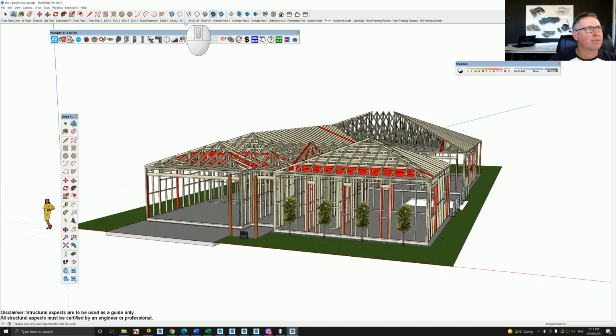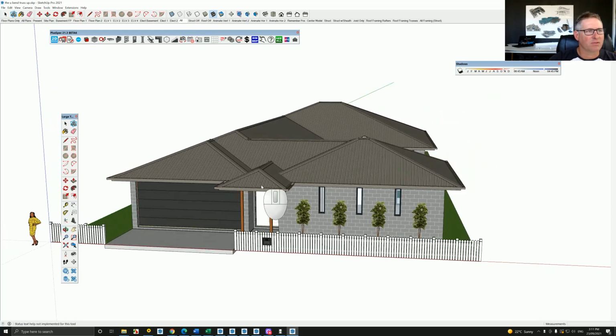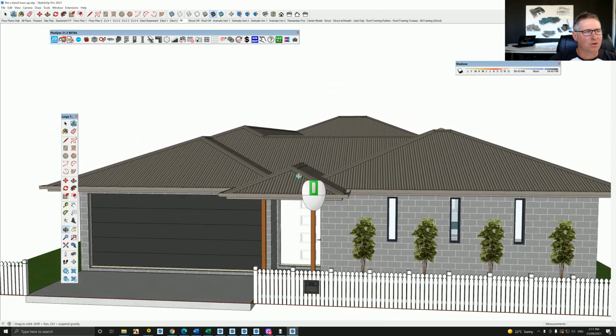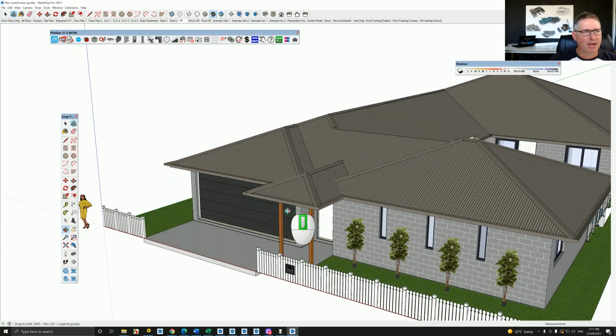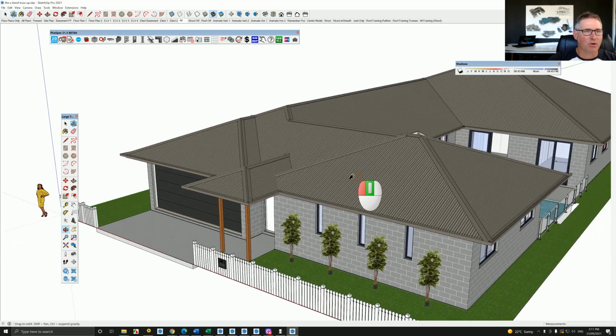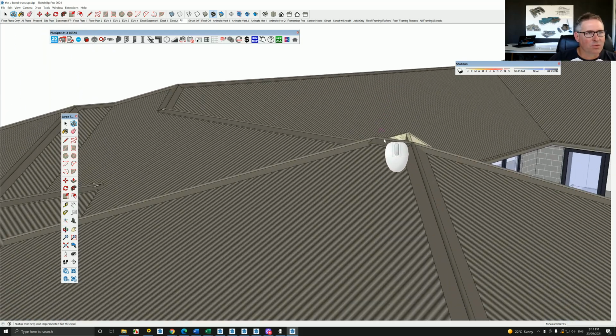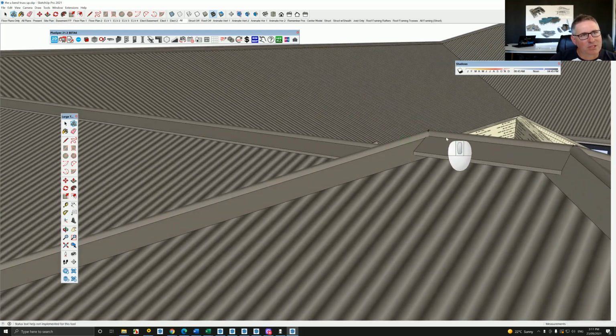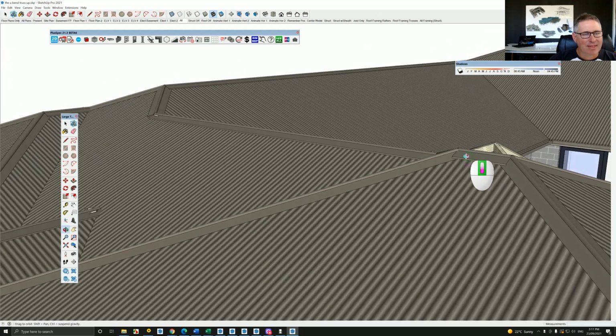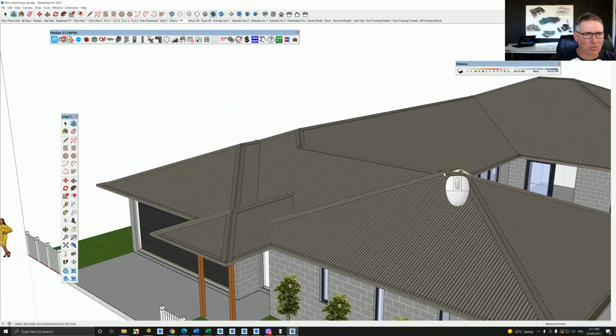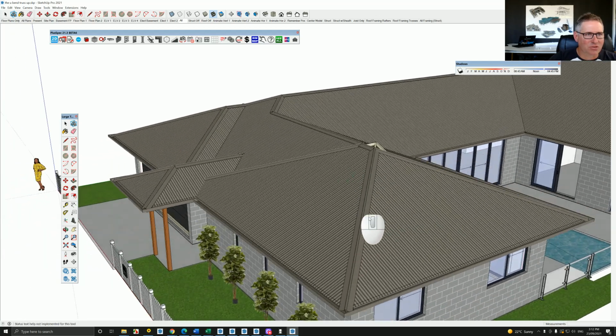However, I think just the fundamentals here of how this roof works is not really how we would do it in the industry. But if that was how you want to do it and you did want to have box gutters, really the issue is that this horizontal piece on top of the roof is called a ridge, and that signifies when you have a flat section which way the roof should actually run. So these trusses should have run from here to here and then back a half span, and that would have actually solved that problem. Let's have a look at the structural side of things.